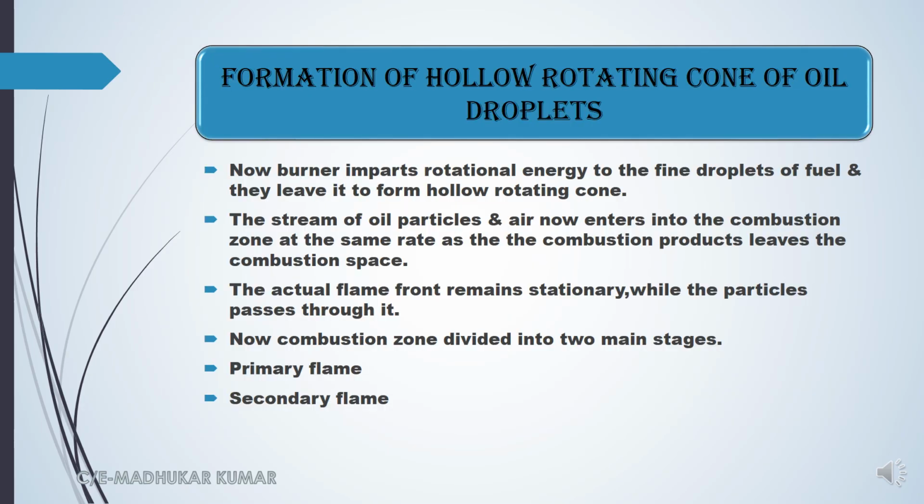Formation of hollow rotating cone of the oil droplets. So now the fuel which is coming out and atomized will form a hollow rotating cone, as we have seen earlier in the video of the pressure jet burner or your normal rotating cup burner. There also we have the hollow rotating cone produced, and this is basically mixed with the air and burned